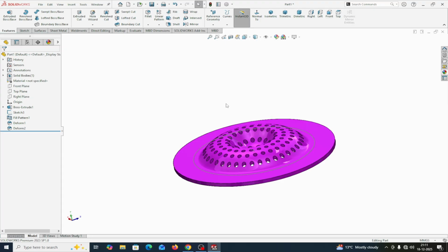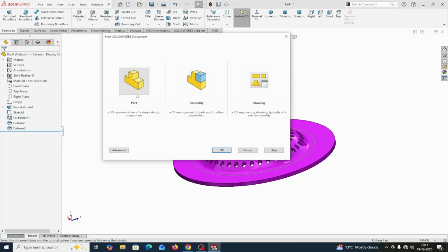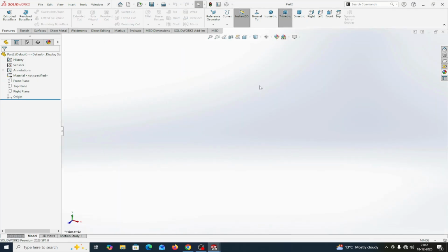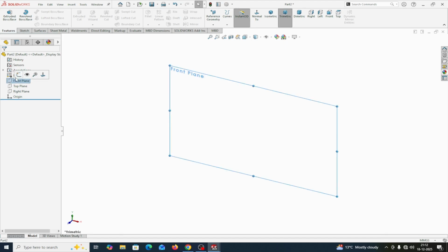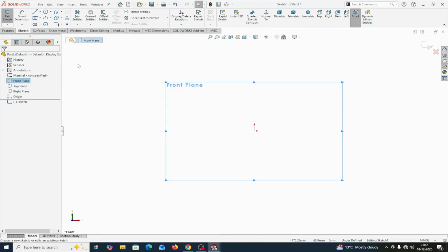Now in the previous exercise I had made one video on the curve to curve option, but one point was left, that is the fixed axis option in curve to curve. For that I make another model. This I am selecting background, and the unit system is the same, millimeter gram second, and this time I am selecting the front plane. I will make a simple model here.